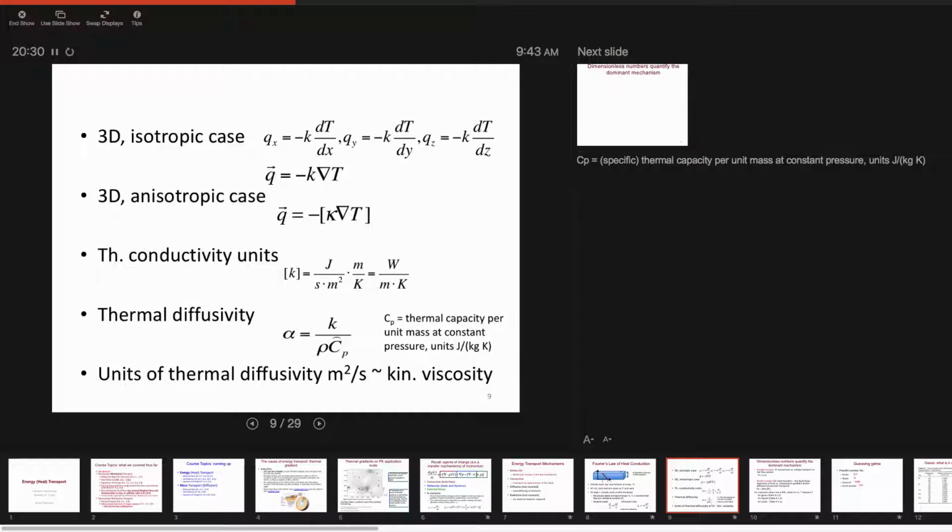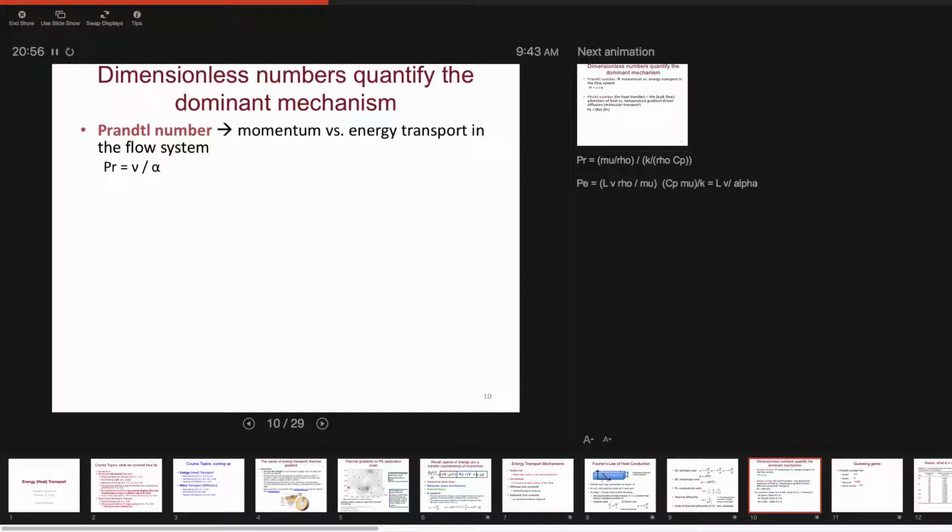And if I have turbulent flow through some large pipe, that's not so difficult to predict. Right? That's convection winning. So in that sense, we always have to evaluate who is the dominant type of transport, so I can be practical and solve practical situations. So for the numbers that actually quantify that, one is called the Prandtl number,